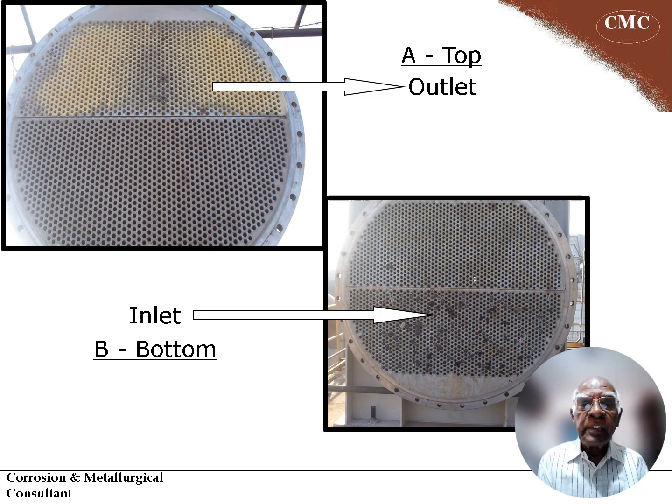So what you see is a series of two shell and tube coolers. The cooling water enters the inlet of the B cooler and then comes out with slightly increasing temperature in the A cooler top outlet. You can see the arrow points, inlet and outlet. That's the cooling water. So in a short period of a few months, a leakage occurred on stainless steel tubes.